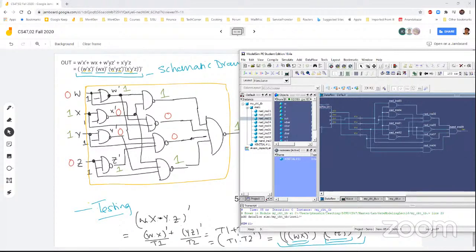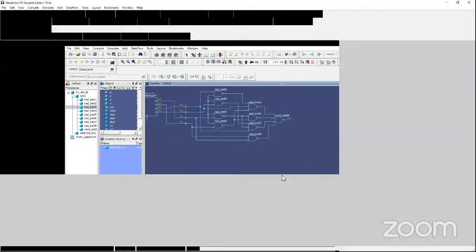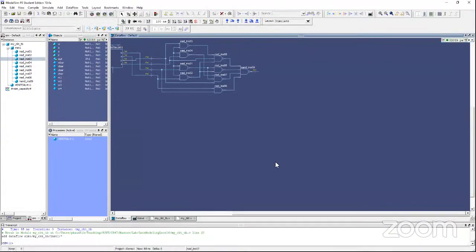So we can somewhat visualize this whole thing within this simulator environment, and also debug. We can inject the values and look at how the logic value is traveling through the logic circuit, and observe if there is any problem that is causing any functional defect or anything like that.